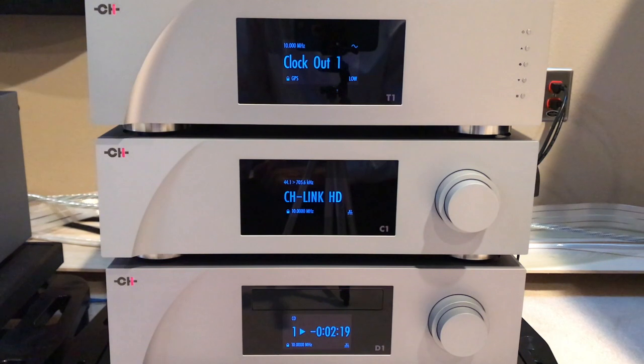You can do that by adding the T1 external clock generator. Remember, the better the clock source, the less phase noise introduced into the clock signal, and the more precise the digital to analog conversion becomes. The T1 has 6 clock outputs that output a highly precise 10 MHz sine wave or square wave clock signal. You can also specify high or low level signal amplitude. An optional GPS tracker and antenna is available to keep the T1 clock from drifting over time, as all clocks do.